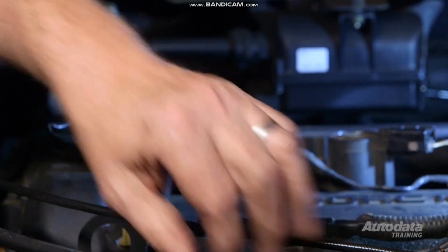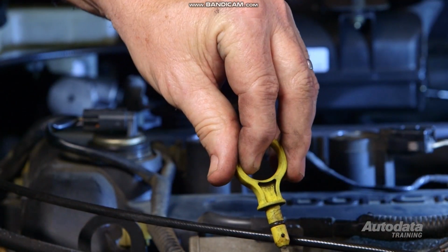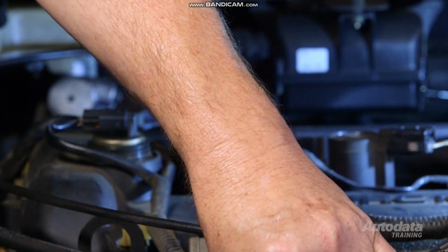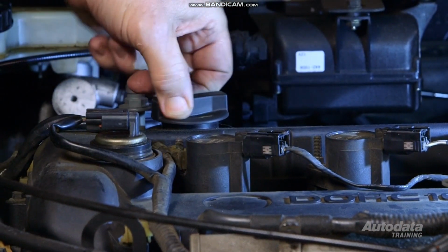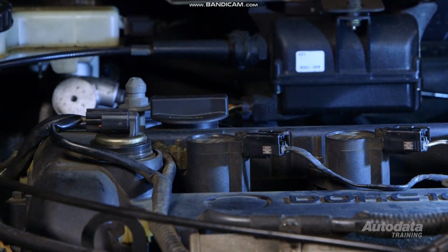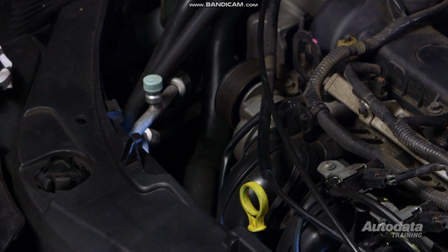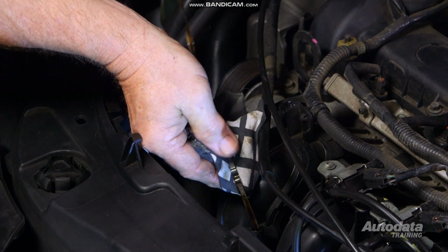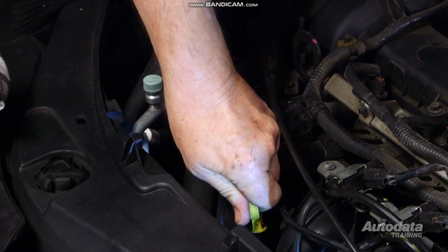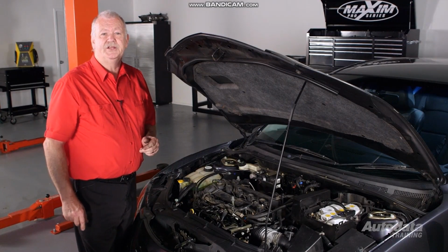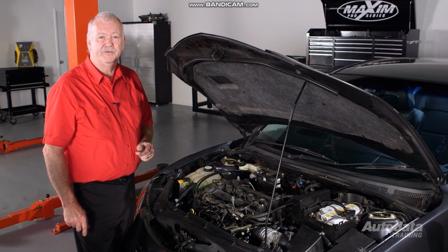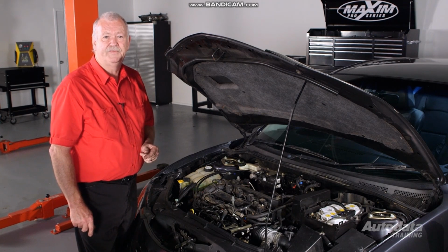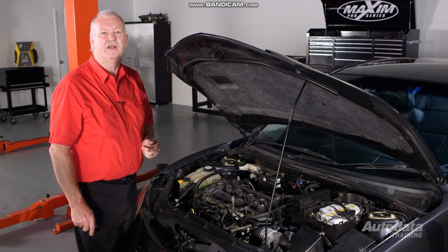An unsealed oil dipstick or a loose or missing oil filler cap can also cause a P0101 or a P0104 to set. While checking the dipstick, also check the oil level, as an overfilled crankcase may be the cause. If any of these conditions are found, rectify them and then recheck for the fault. If none of these faults are evident, you'll need to carry out the following electrical procedure.